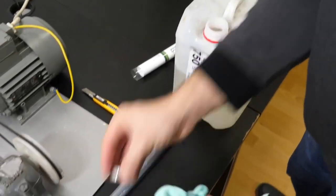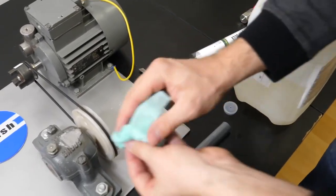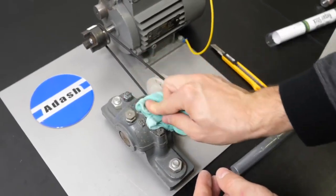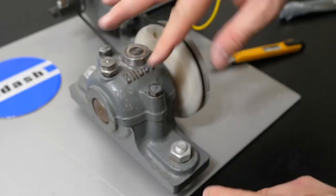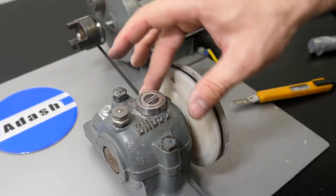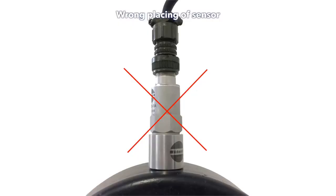For mounting the measurement pad, it is important to clean the machine surface. This means removing paint and rust with a grinder and degreasing with solvent. Then cut the glue. Mix the two glue components between your fingers. Glue the pad. After 24 hours, the pad is ready to use. Avoid just placing the sensor on the bearing housing without the glue. The flat magnetic base will rock on the rounded housing surface, and such a measurement is useless.